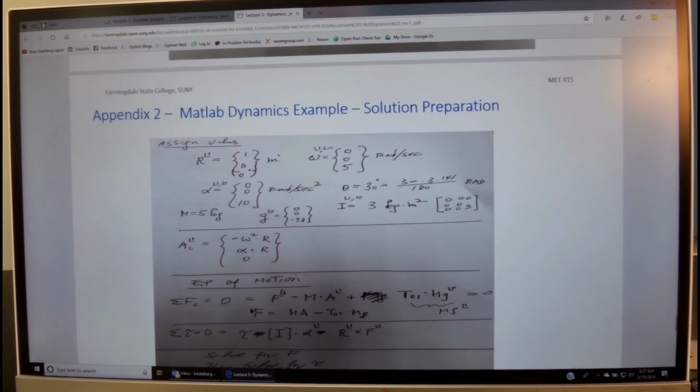we do all of that. For example, they're all in the inertial frame, but we can resolve it into any other coordinate system. Here, for convenience, we resolve it into the body fixed coordinate system, and therefore we have to transform the mg, which is defined in the inertial frame, into the body fixed coordinate system with this matrix of transformation, and it has a minus sign here when we move it to the other side.